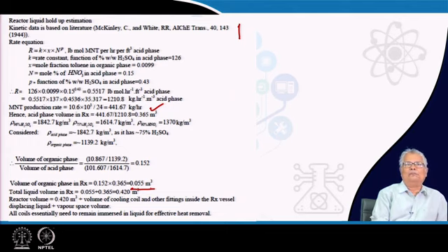Now, there is something. The reacted volume will be how much? The reacted volume will be 0.055 plus the inorganic volume, which is basically the aqueous volume of the acids, which is making a large part of it. The proportion of the aqueous phase present in your reactor is much large as compared to your volume of the organic phase. This is primarily required to limit the concentrations so that you get your desired distribution of products.